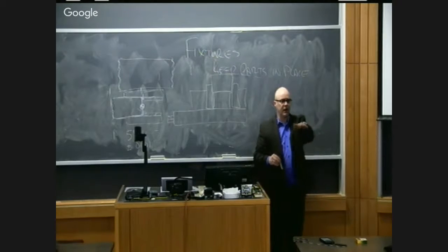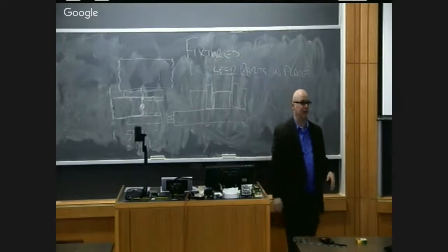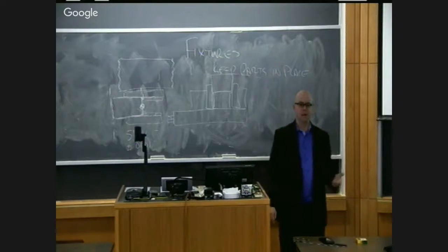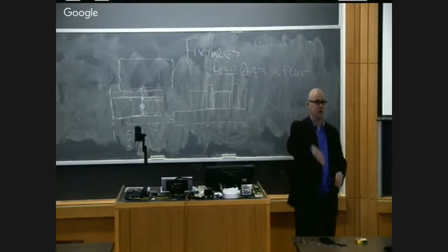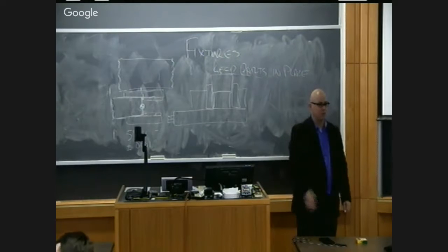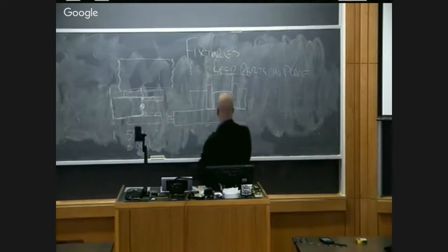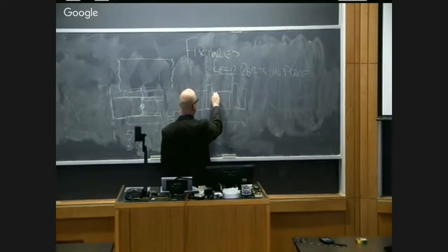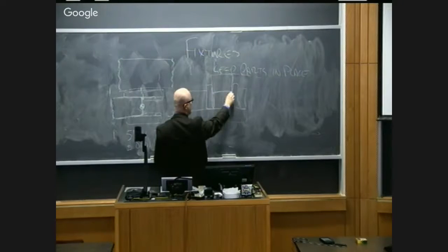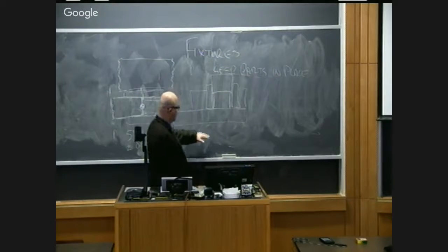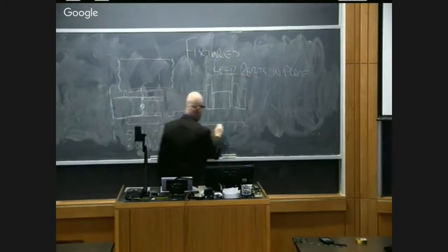Right, so if you put it in there, you can eyeball it to be even with the top edge of the vise jaw, maybe that's your reference that you can see. The top edge of the vise jaw is not necessarily perpendicular to the motion of travel. It's not necessarily parallel with the machine tool. So our parallels are intended to keep both sides of this part the same distance from the table in the machine tool.